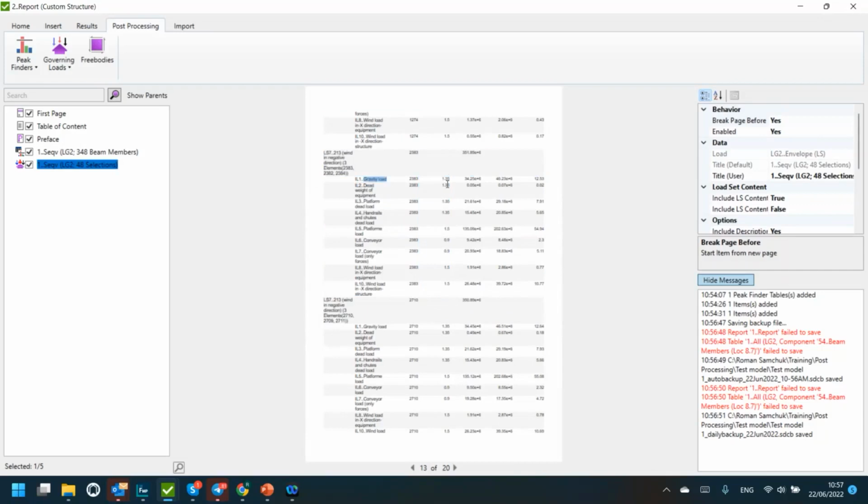So in this table, you see the factors in the load combination, you see the net stress value in the load, and then increased stress due to these factors and the percentage influence. That gives you a precise understanding of why it happens, what you need to do to improve it, and maybe you need to improve your loads, because you might assume conservatively a certain value of your load, and you can reduce them to a more realistic magnitude. So that is the whole idea.